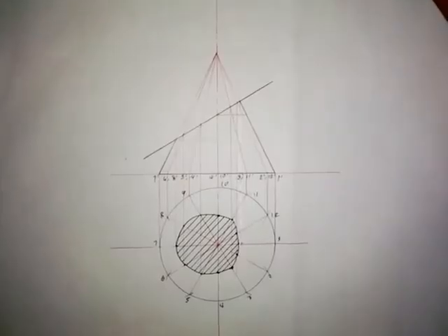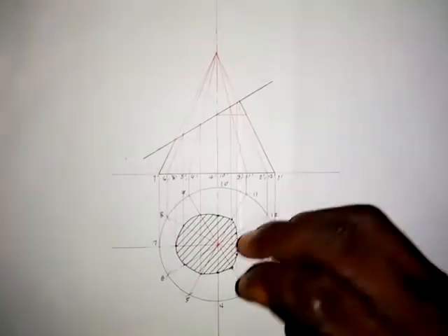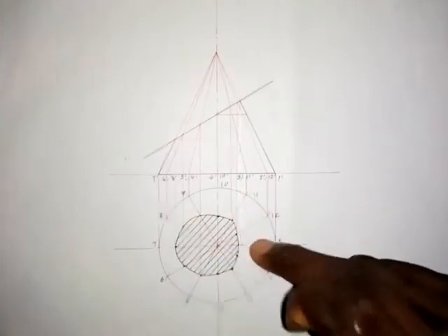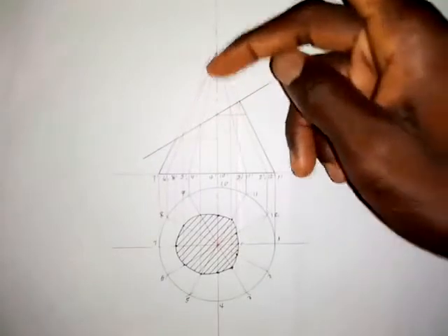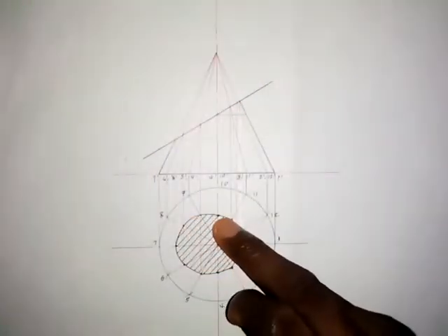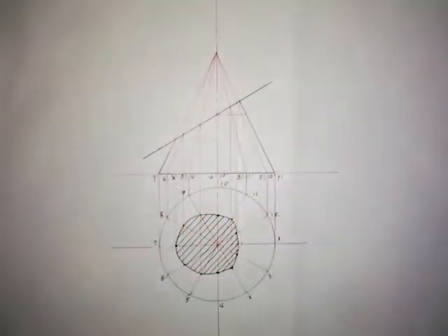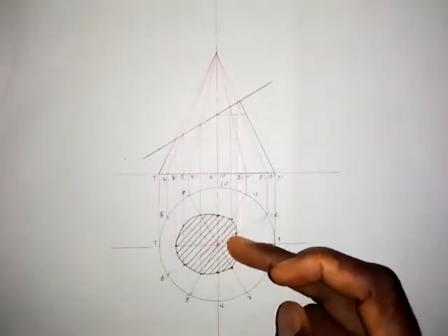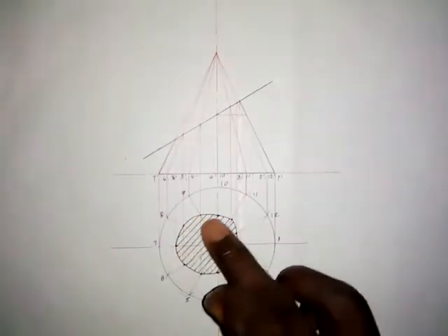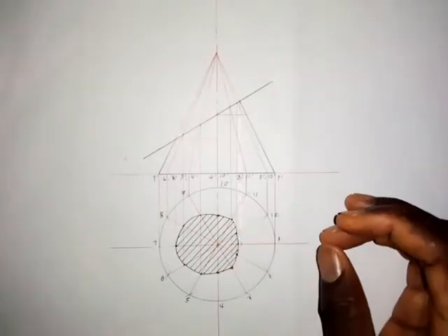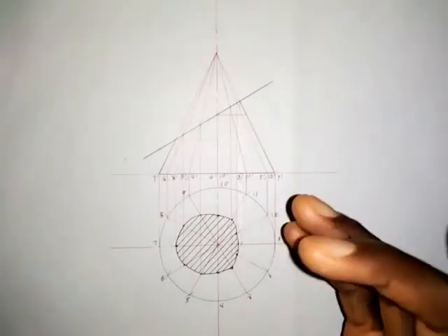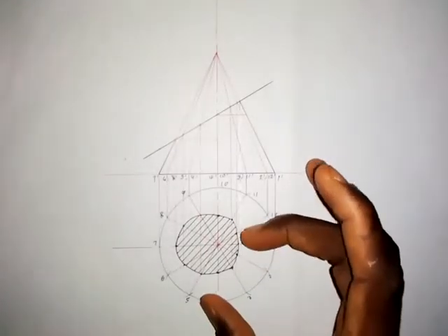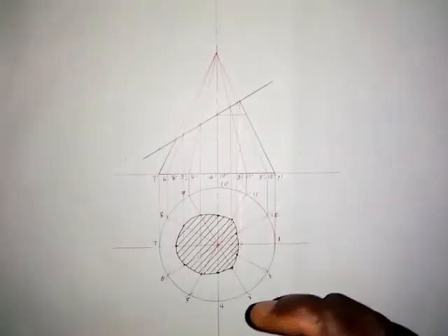All right, so we have answered question B, which is for us to draw the complete plan. So this is the complete plan now. The roughness of this surface when this part is removed is what is shown here. After you have joined the points together with the use of the French curve, you need to draw these lines known as arching lines. We draw the arching lines with a 45 degrees set square. The arching lines are thin continuous lines, and they are parallel to each other and also equally spaced.